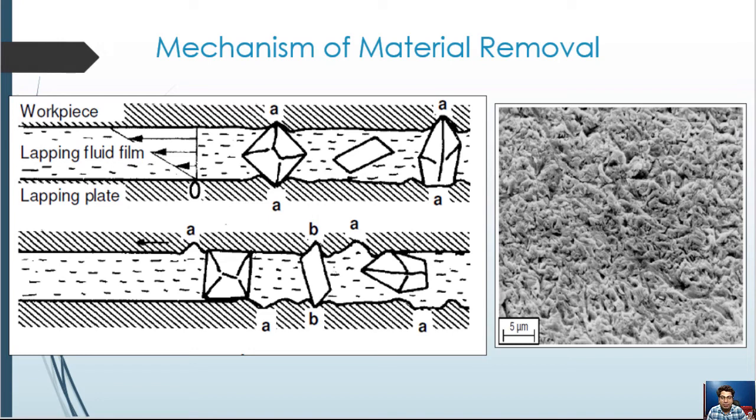The lapping disc produces a rotatory movement and serves as a carrier for the lapping slurry, workpieces and dressing rings. The rotational speed must be measured so that impermissibly high centrifugal forces are avoided. Otherwise, the grains might leave scratch marks. The lapping disc is generally made of special fine-grained pearlite cast iron material or of hardened steel alloy.